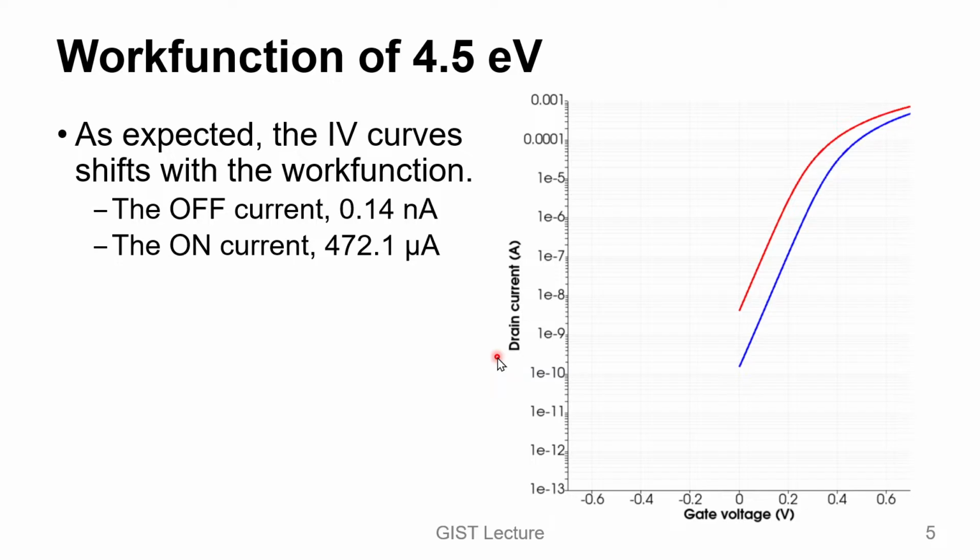However, in our implementation, we have just pure silicon dioxide with a given thickness and tungsten film. So basically, work function cannot be adjusted that way. So we must use this work function as just a fitting parameter to match our IV curve.